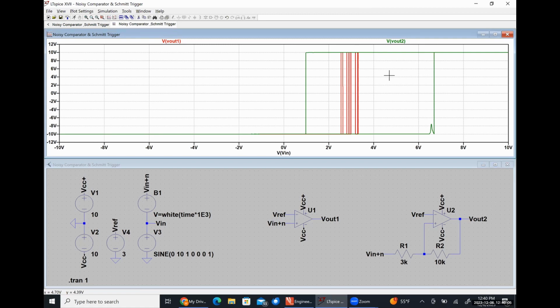So we can see here that our output signal effectively changes states when our input is around 1, and then over here, somewhere between 6 and 7. We're going to see if we can figure out the math behind why these particular resistor values cause our output to change states at somewhere around 1 and somewhere around 6.5-ish, instead of the 3 that we would expect because of our reference voltage.